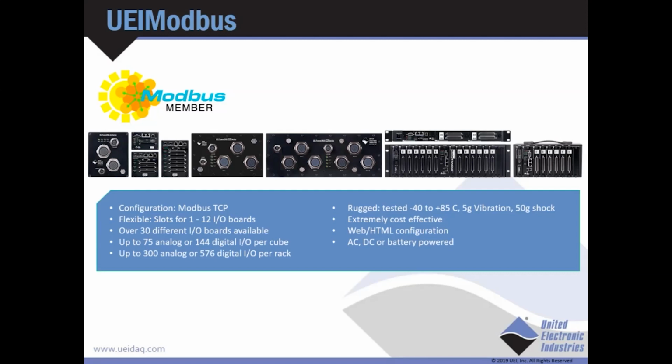We have over 30 different I/O boards, so whether you need something for accelerometers, thermocouples, or RTDs, we should have that board covered. We're also very rugged, so if you need to cover extreme temperature range, vibration, and shock, we have that covered as well. Soon I'll show a demo of how you can use our web configurator to configure the Modbus TCP server without having to write any code.